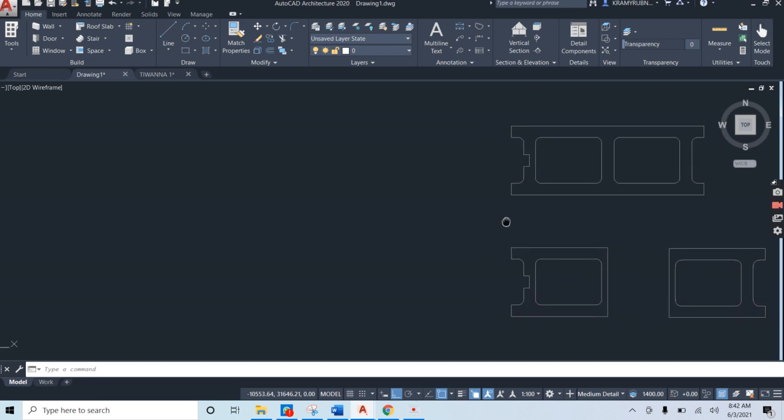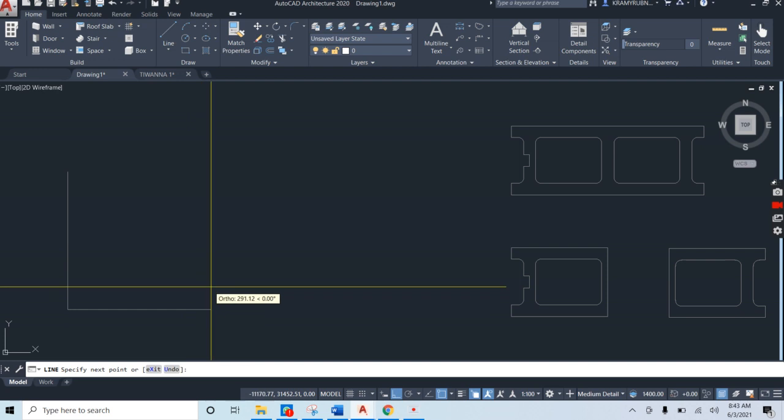You would already be aware of the dimensions of our stiffeners, but let me remind you that for our L stiffener, I'm going to be using our line command. Our L stiffener is 300 millimeters in one direction. So let's type 300. It is 300 in the other direction as well.